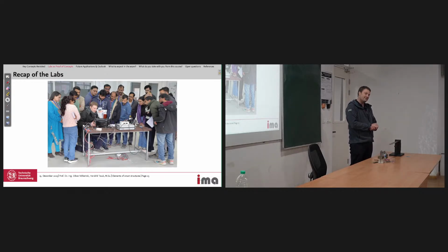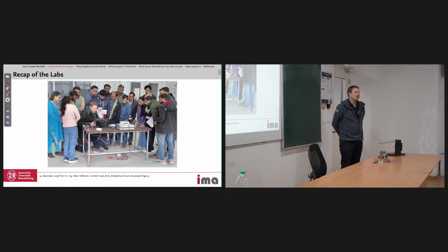So, what I didn't tell you today is that this setup is not perfect. The eigenfrequency is actually a little bit higher, because if I hold it here, can you see how the beam shifts? Yeah, so it's not a perfect clamping, because this is not stiff enough, because it's plastic and not steel as it's supposed to be, but then steel was too heavy to bring. So actually the frequency would be a bit higher if that would be stiffer. Okay, so small mistake, but nothing which changes the principle of how it works.